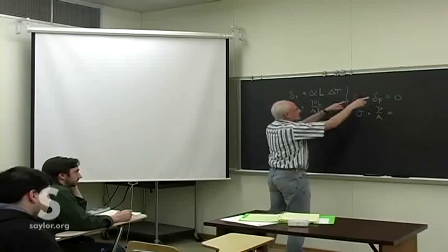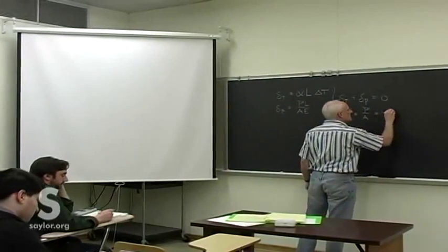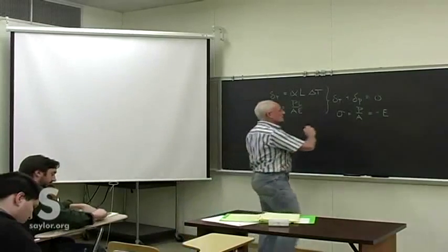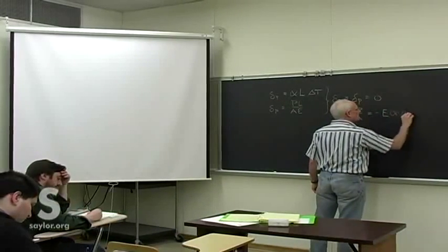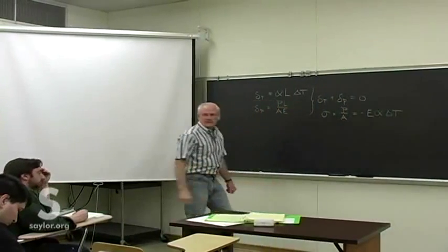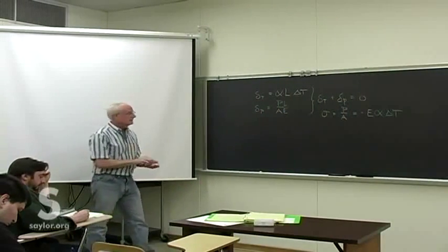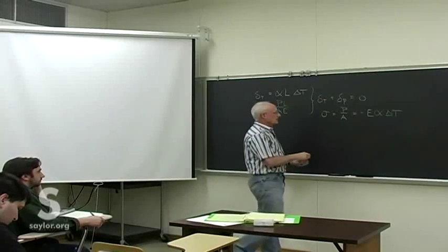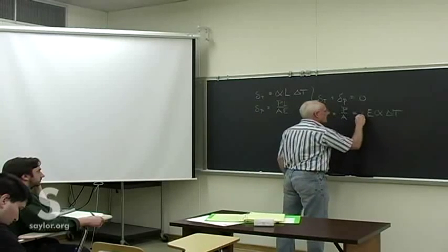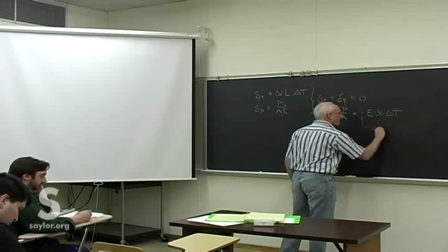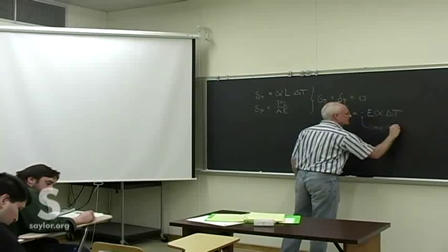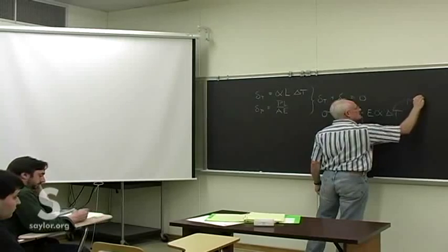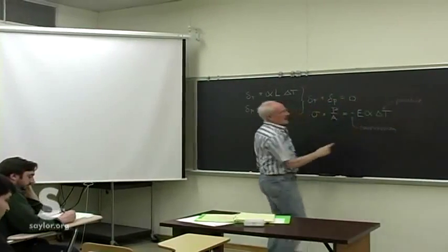So when we put these two in there and solve, we get something like minus E, which is, as always, Young's modulus, alpha delta T. The minus sign works, well, algebraically it comes into the piece anyway because of the original equation. But it does give us a compression if the temperature change is positive, and vice versa, which is exactly what we saw there.